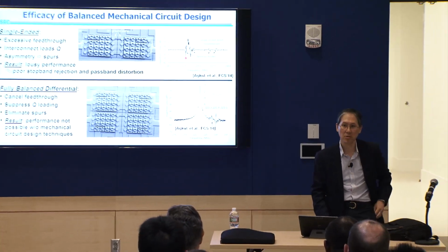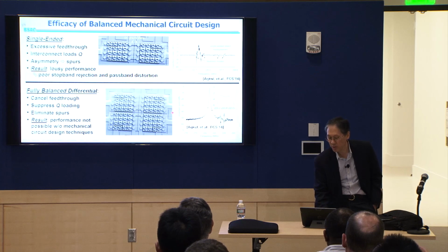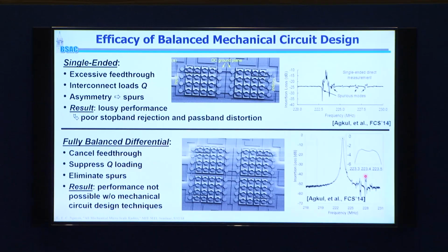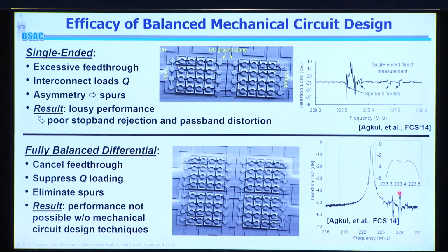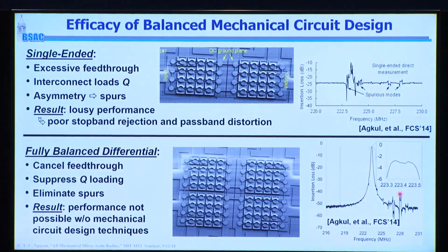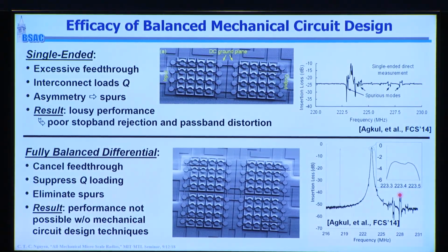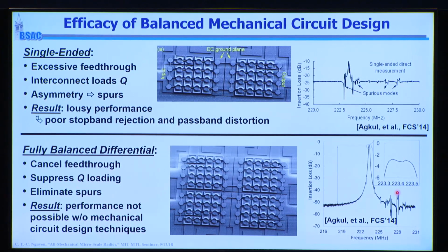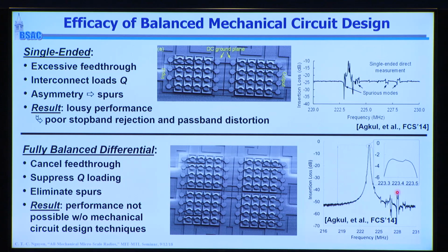Make it symmetrical. Because this symmetry not only gives us all this, but it takes those spurious responses and sticks them all the way down. And if you're an FBAR designer for Broadcom, who again are making gobs of money doing this stuff, the secret in the pudding is not necessarily the technology. The secret is how to get rid of those spurious modes. That's why they're able to sell so much. That's why they can lock other people out of this game,